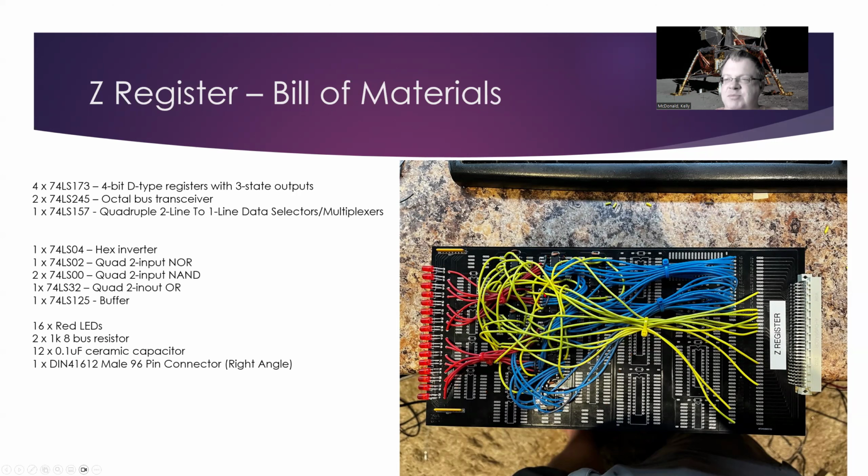That's one of the nice things about building everything onto a standardized board: I can put these little filter capacitors really close to the power inputs on each and every chip so that they're nice and happy as they operate. And then I've got this connector. I'll talk about this more in one of the next videos around the actual design and logic of how I've laid out the hardware. But I'm using this 96-pin connector to run most of the signals in and out of the computer.